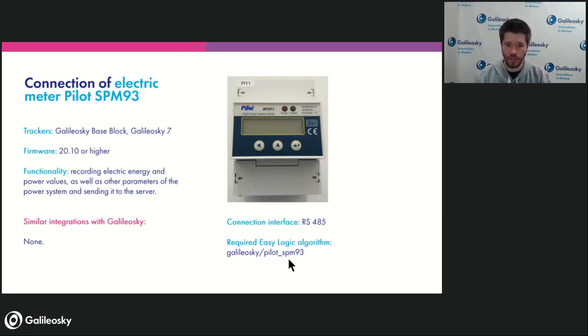For example, you can set using EasyLogic different notifications if the levels are reaching higher or lower than certain values, and notify the according people who should take measures to work with that situation, or simply try to make some actions autonomously using the outputs of the tracker and using system of relays, for example.